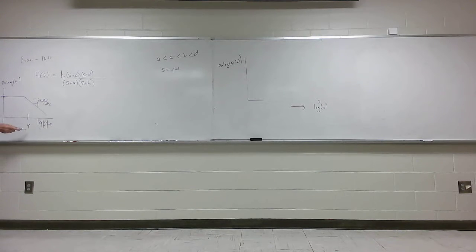When we're right here, actually the real curve is a little less than this. This will be 3 dB difference, and here's why. When we're at S equals A, actually S would be jA, right? It's when jω equals S. So this would be jA over A, or just j plus 1, wouldn't it, class? What is the magnitude of 1 plus j? Magnitude. It's square root of 2, isn't it?